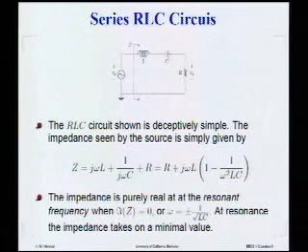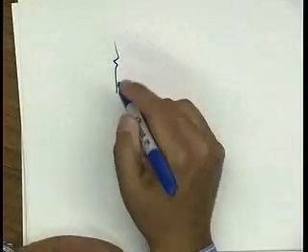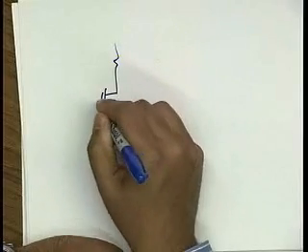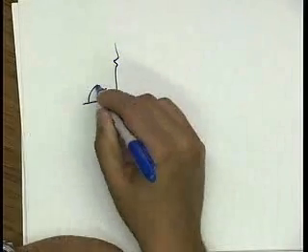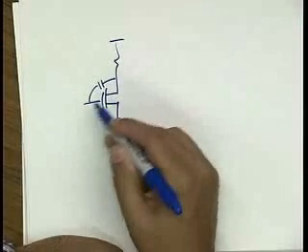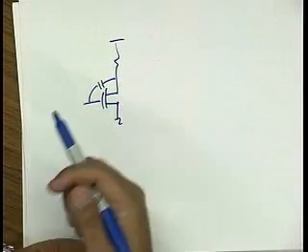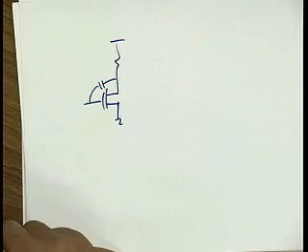I'd like to tell you guys about tuned amplifiers, but I just want to remind you about series and parallel RLC circuits. Before I do that, let me introduce this topic a little bit. Up to now, we've been talking about designing amplifiers using Rs and Cs, right? So we have an amplifier like this. And we found that lots of RC time constants come into play and limit the bandwidth. You may ask, well, why not use inductors?